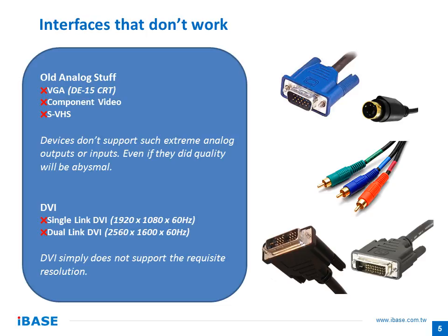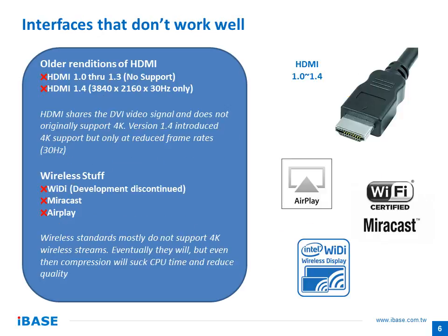Now DVI, good old DVI, does not support 4K. DVI comes in 2 forms, single and dual link, and neither of those go to a high enough resolution. So that brings us to some of the interfaces that are more recent. Now we have HDMI. Every screen or projector or whatever it is that you have out there will have an HDMI connector. Okay, but all HDMI are not created equal.